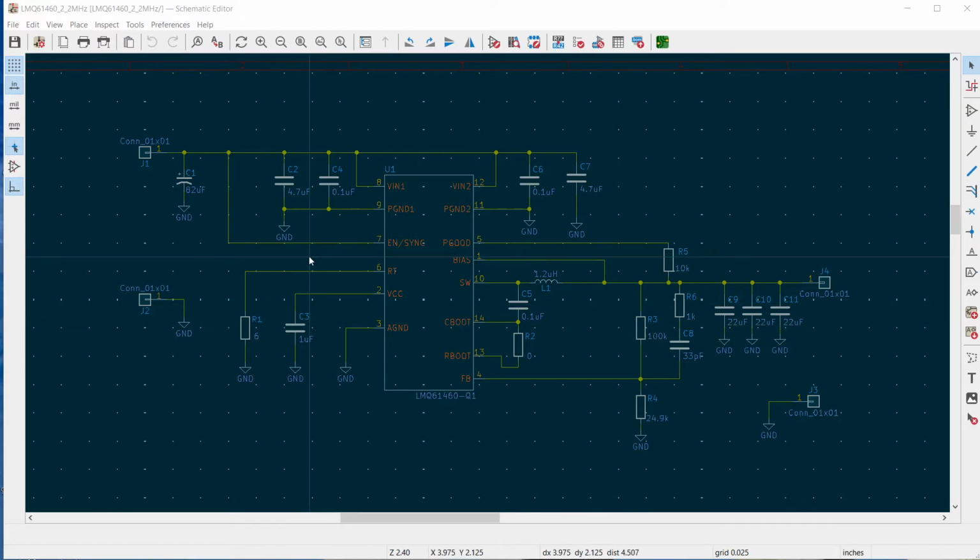So to start with, I'm going to assign all the footprints for ones that KiCad already has in its built-in libraries. So that's going to be some of the standard capacitors and resistors and things like that. And then there's about 4 parts. We have the banana jack plugs that we're going to use. We have this electrolytic capacitor. We have the regulator component itself. And we have the inductor. Those ones are kind of non-standard. There's not really industry standards for them. So we're going to go through, look at the data sheets, find the footprints, and design our own.